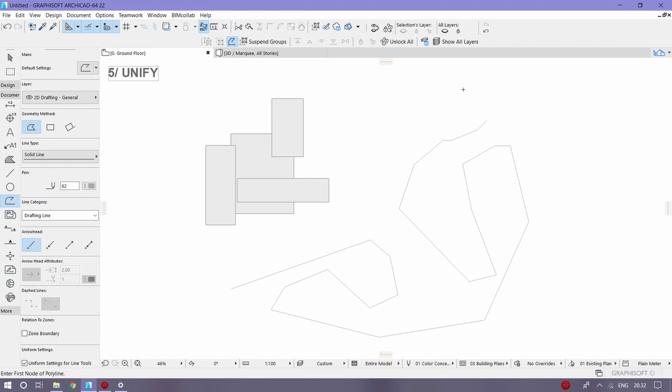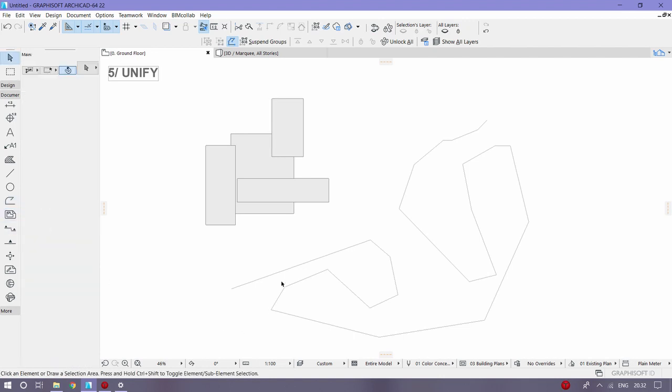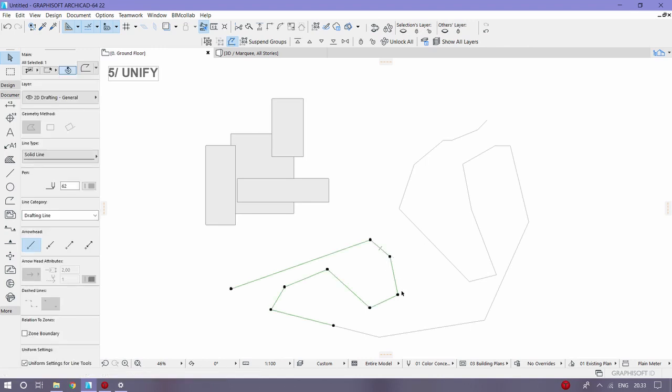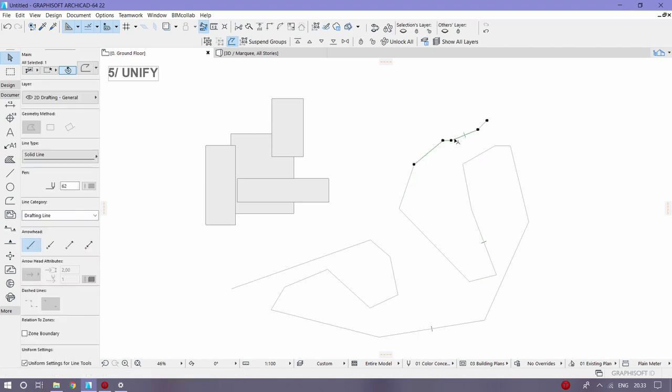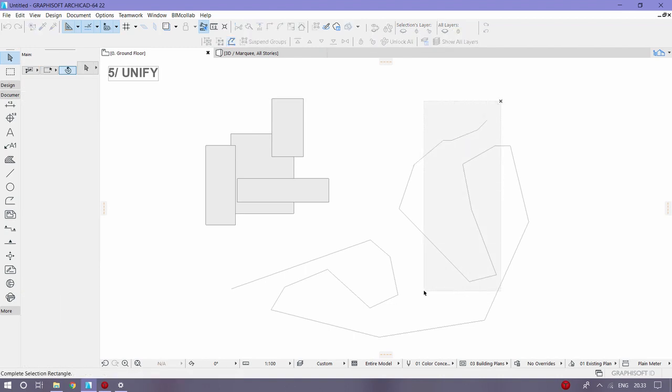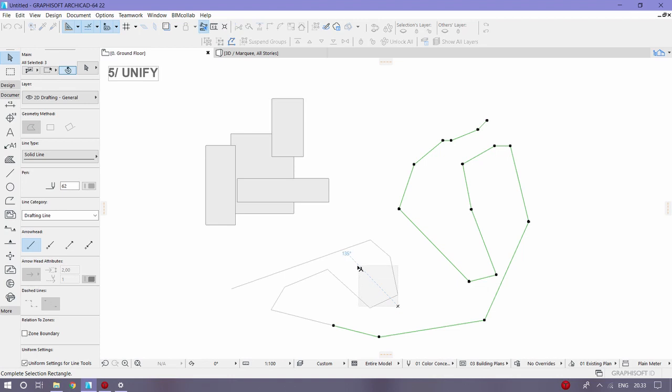You can use all fills and the polylines. So here we have, let's start with polylines. Here we have different kinds of polylines all connected in the same dots or chained, I guess, but you want to make it just one polyline. This is really useful if you export PDFs into current views and they have multiple polylines that should be just one line.